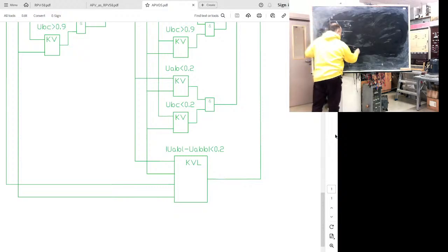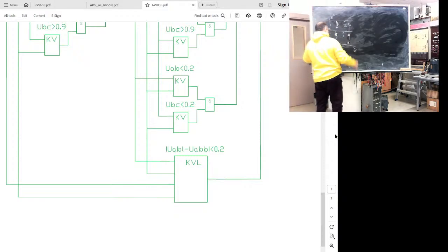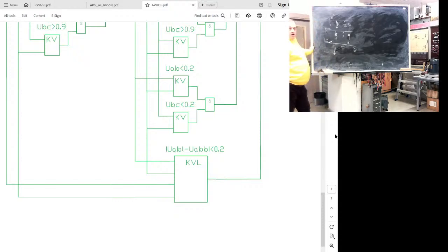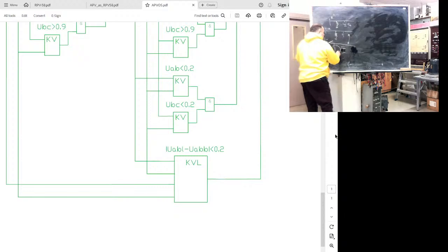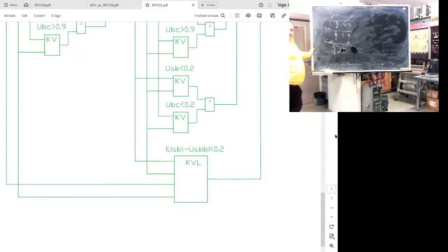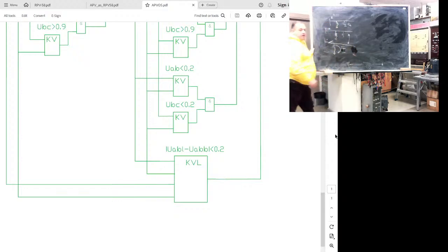You have, for example, a fault, it's disappeared, the switch is disconnected, but through line-to-line capacitance, voltage can be supplied, and line capacitance can supply enough energy that in this contour, line capacitance and shunt reactor inductance, a resonance oscillation will remain. And this will keep a secondary arc at the fault place.